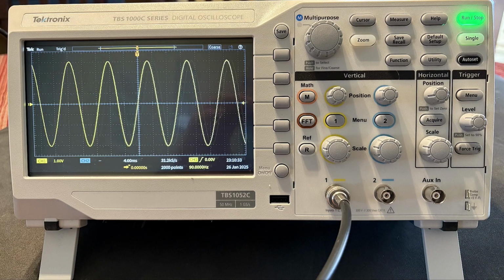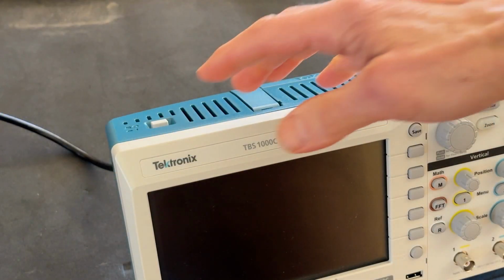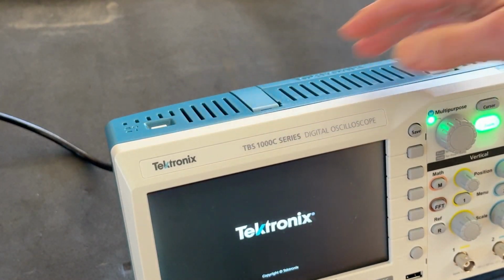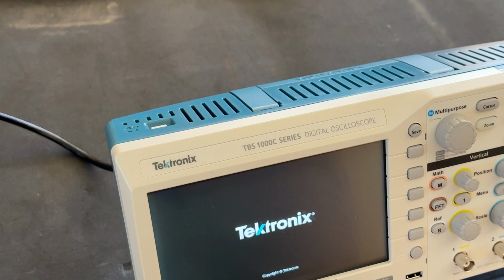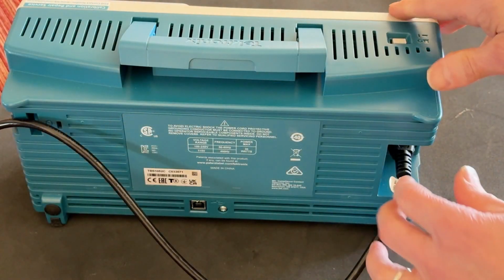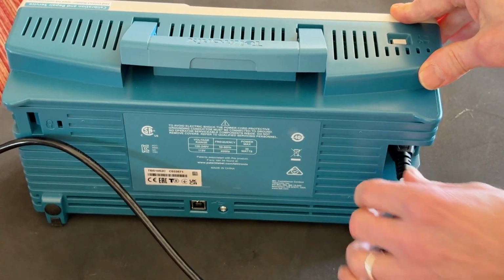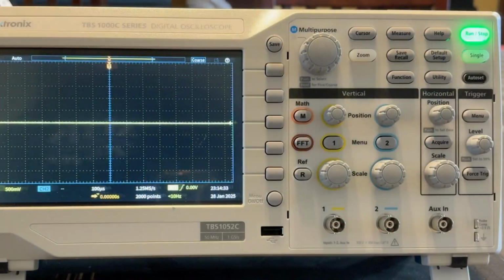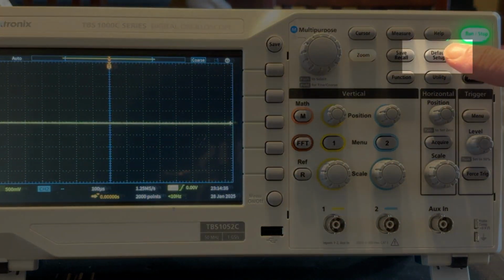Now that you know how to find the amplitude and period on the screen, let's look at how to actually operate the oscilloscope. Although there are many buttons and knobs on the scope, we will only use a few of them. We already spoke about the vertical and horizontal scale knobs, as well as the position knobs. To turn on the scope, you'll push the power button. If the scope doesn't turn on, check that the power cord is all the way in and plugged into an outlet. Once the scope is on, press the default setup button.